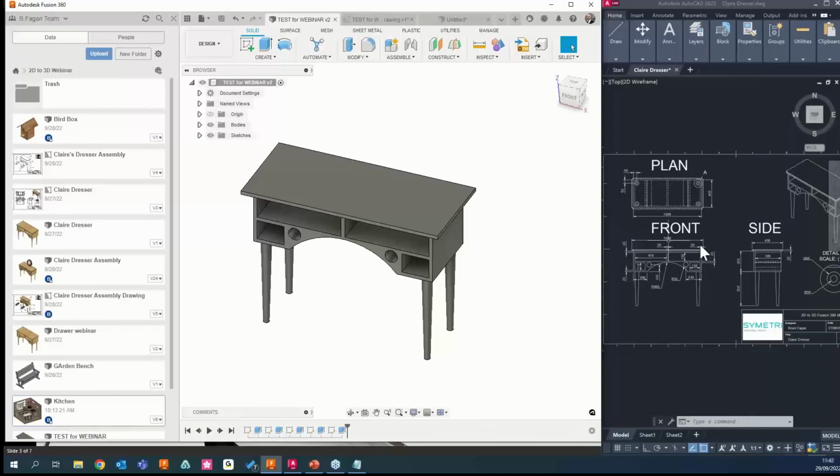So you're doing the same in Fusion 360 by creating sketches, but you just don't ever end up making them into 3D. So you're doing the same purpose. You're making a 2D drawing and then you're just going to extrude that 2D drawing and then you're going to put another sketch on the side of that 2D drawing, or on the top or on the bottom or an edge, etc.